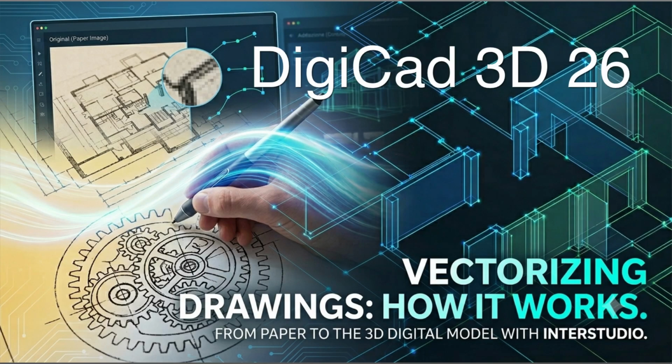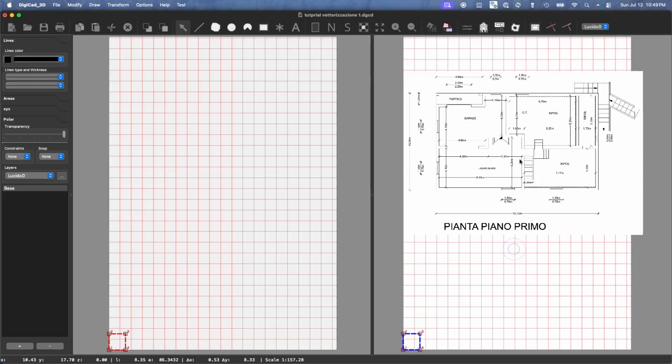Drawing vectorization is optimized to extract vector drawing elements from scans of old drawings even in poor condition, such as plant cadastral maps or old heliocopies. I select an imported image and choose the Vectorize Drawing command.